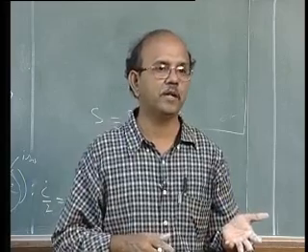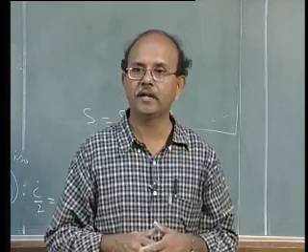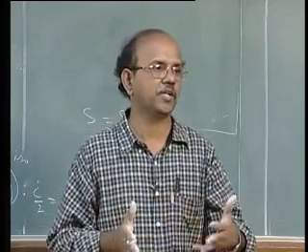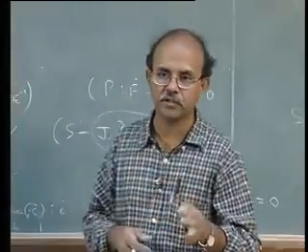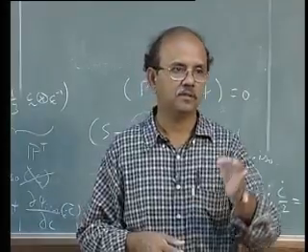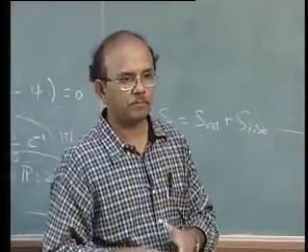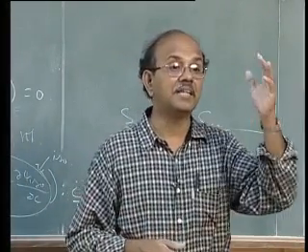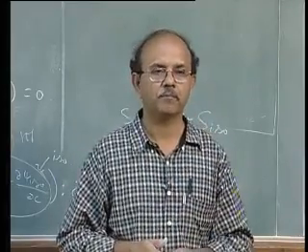So when we came to incompressible hyperelasticity, we realized that we have to put J as a constraint, J is equal to 1. So what we did was to add to that strain energy function a constraint condition through a Lagrangian multiplier, P times J minus 1. We did that, and then the rest of it followed in a very similar fashion as we did in the first case.